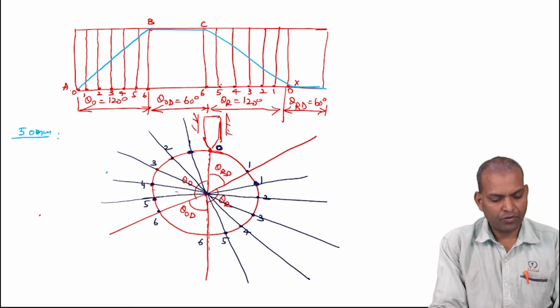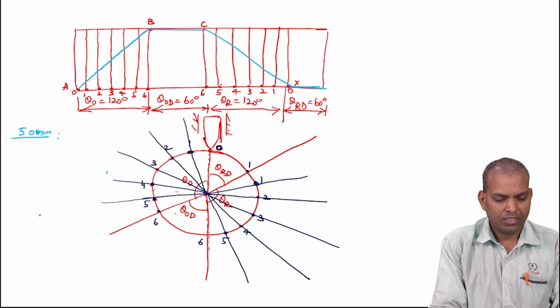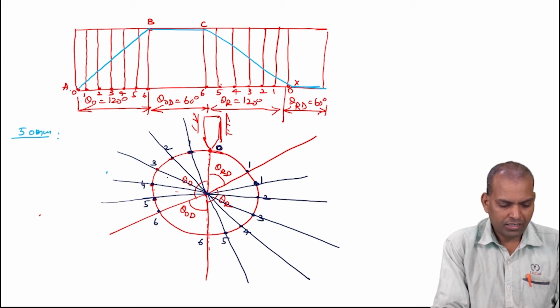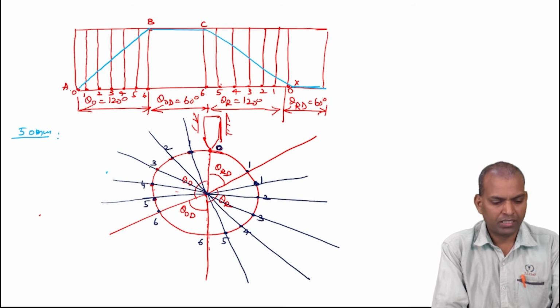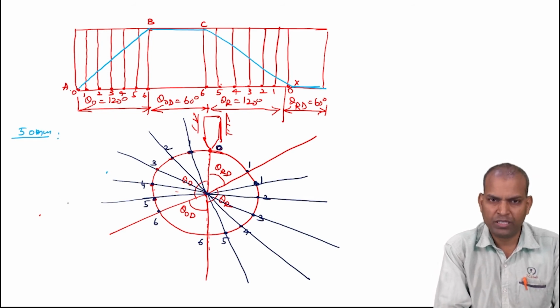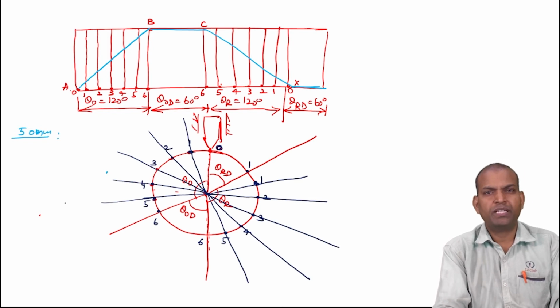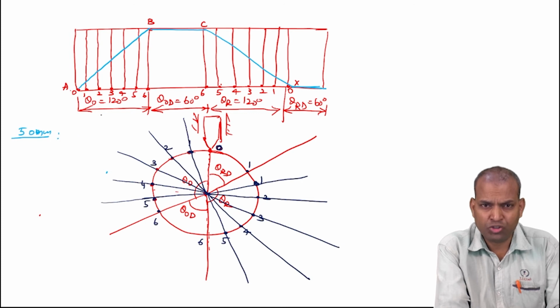So how to divide the outward stroke? Into equal angular divisions; with the help of a protractor you can divide. Similarly, the return stroke can also be divided into equal parts. Now we have divided into 6 equal parts. It can be 8 also, but it should be the same number of parts you divided in the displacement diagram. In the displacement diagram, the outward stroke is divided into 6 equal divisions.